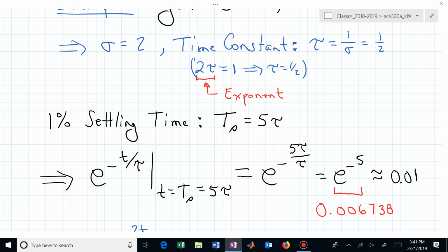In this case, if our circuit actually had a time constant of 1/2, we would say, well, essentially, the waveform is gone when we have crossed 5 time constants, or how much time? 5 times 1/2, 5/2, or 2.5. So in 2.5 seconds, we essentially have all of our transients gone from our circuit.